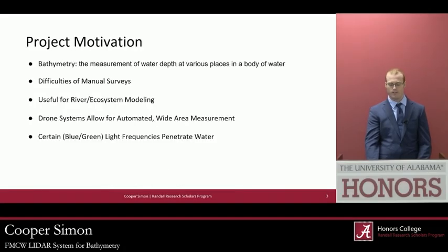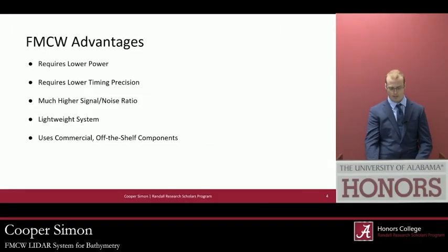Bathymetry is the measurement of water depth at various places in a body of water, and it's difficult to do manually with enough data depth for river or ecosystem modeling. Drone systems allow for automated wide area measurement, and certain blue-green light frequencies can penetrate water, making LIDAR a viable option. FMCW offers the advantages of lower power and timing precision requirements, while offering a much higher signal-to-noise ratio and being lightweight and using commercial off-the-shelf components.